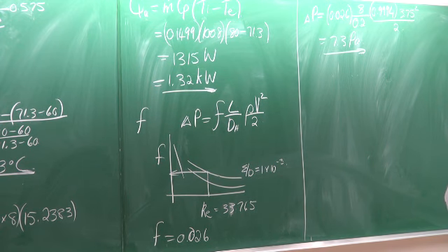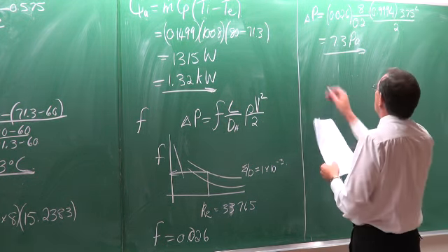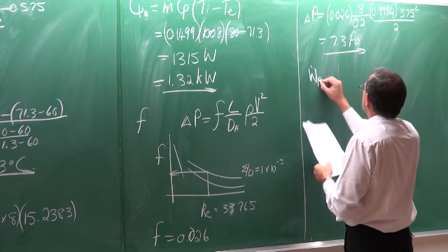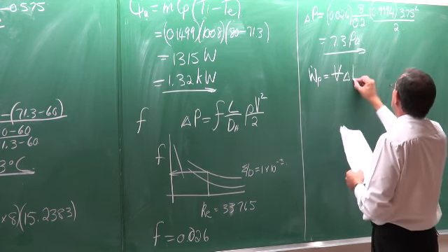Right, so that is the pressure drop, and then lastly we can also calculate the fan power, how much energy must be put into the air to get that flow rate through that tube, and we can calculate it as just the volume flow rate multiplied by the pressure drop.